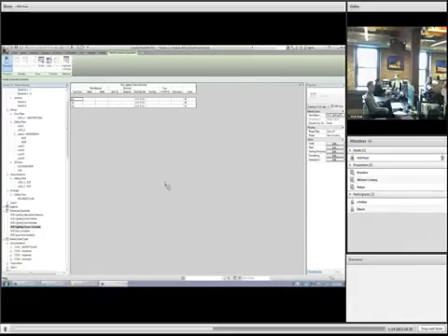So on the fly, we can say, we're an interior designer, we do lots of interior layouts, and our furniture needs to contribute to a LEED credit. We're going to suddenly add that data parameter to every piece of furniture, so that as a piece of furniture is utilized throughout the project, it carries a piece of data. It can be filled in manually for what credit it applies to. And we can do the same for lighting fixtures. We can just say every lighting fixture in this project needs to carry the ballast code with it. And you can do that fairly quickly. You don't need to go into the lighting family.